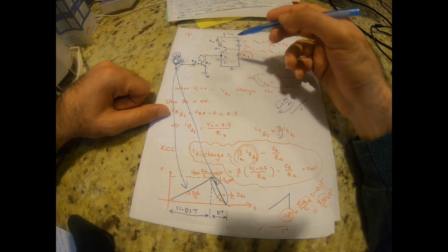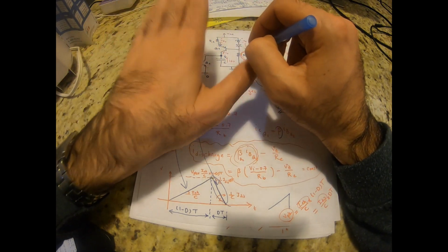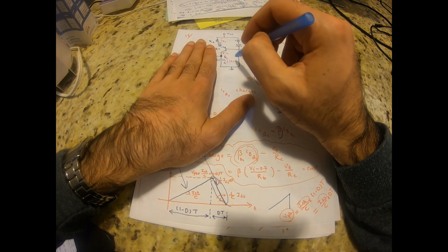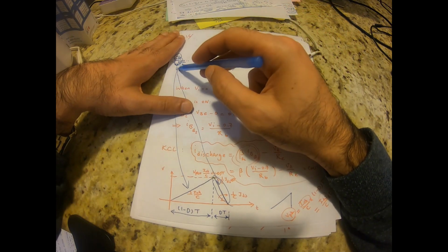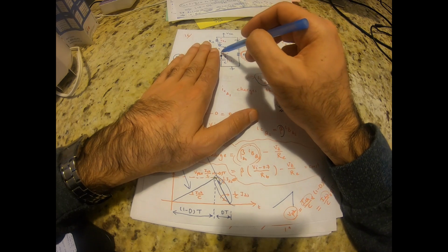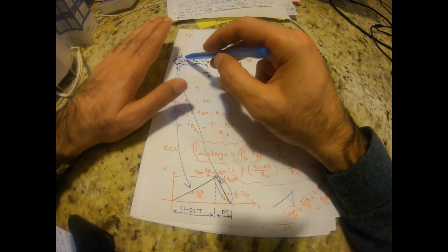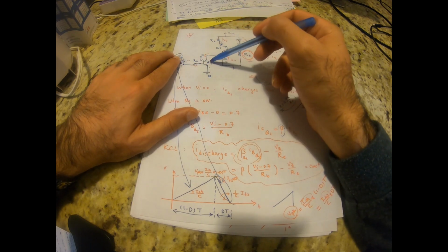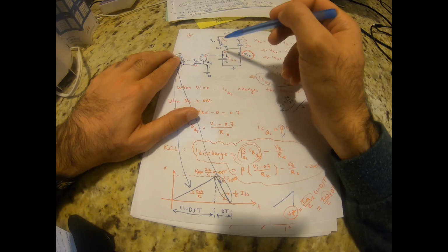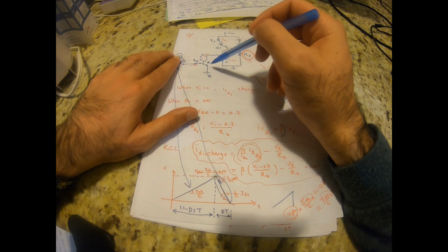So when do we have charging? When this part of the circuit is not active, right? So when the input voltage is equal to 0, the capacitor is going to charge. When the input voltage becomes, let's say, 10 volts or 5 volts, then this switch is on, and you would have this discharging current that goes through to the ground through here.